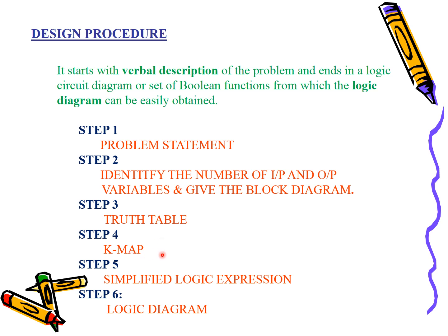That is to simplify. There are three methods. You can go for either laws and rules or the theorems, or you can go for the Karnaugh mapping method or the tabulation method. Always, if it's less than 5 variables, we prefer K-map. So we go for K-map. From that you will obtain a simplified logic expression. From the logic expression you have to plot your logic circuit. Okay, so this is how the design procedure goes on.